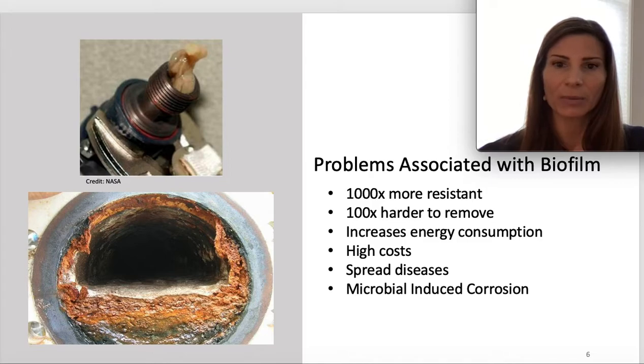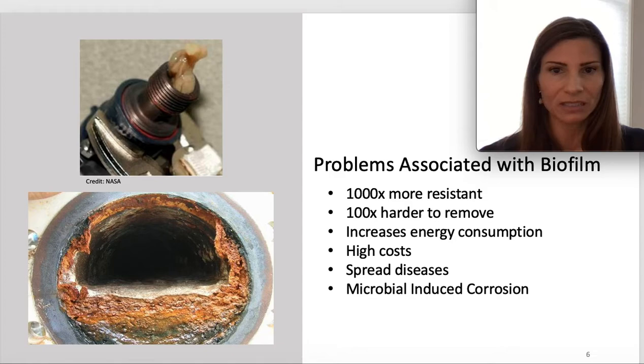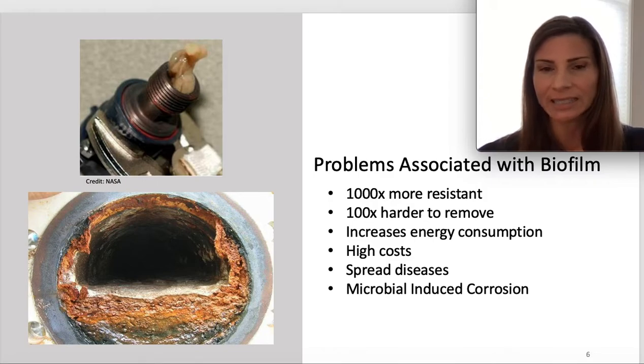Biofilm has become such a problem in hospitals that in the US, they've removed the sinks from doctors' offices and patients' rooms because the pathogenic bacteria can live in the sink pipes and reinfect patients. In addition, microbial-induced corrosion is associated with biofilm. It's due to the bacteria in contact with the surface under the biofilm that causes serious corrosion. In addition to damaging the pipes, when this corrosion occurs on copper pipes, it can release high amounts of copper into the water, exceeding the maximum allowable concentration.